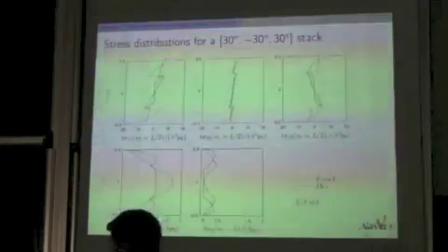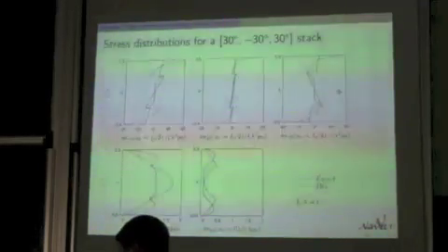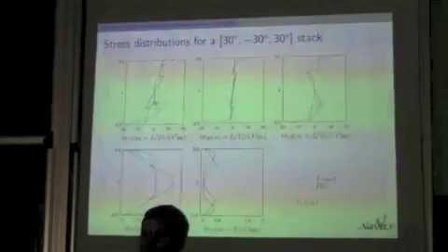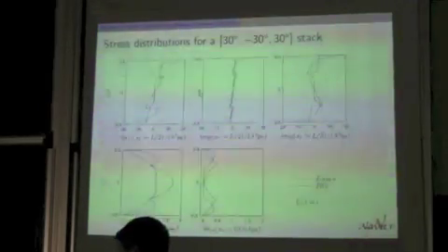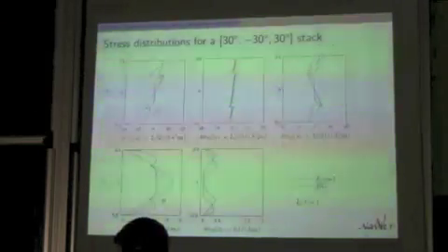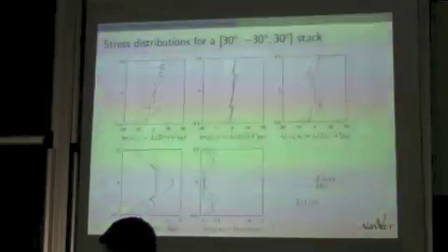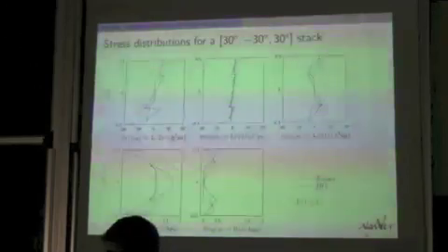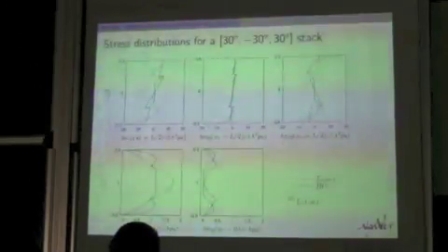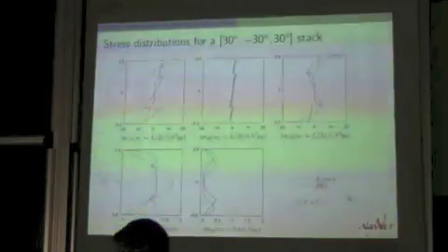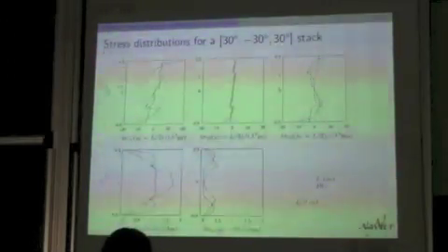So the three upper plots are the in-plane stresses, the bending stresses, sigma 11, 22, 12, and these are the transverse shear stresses. They look ugly. The blue is the exact solution, and the green is the approximated solution. They look ugly, but look, the slenderness is 1. So 1 is not slender for me. I don't know for you, but for me it's not slender.